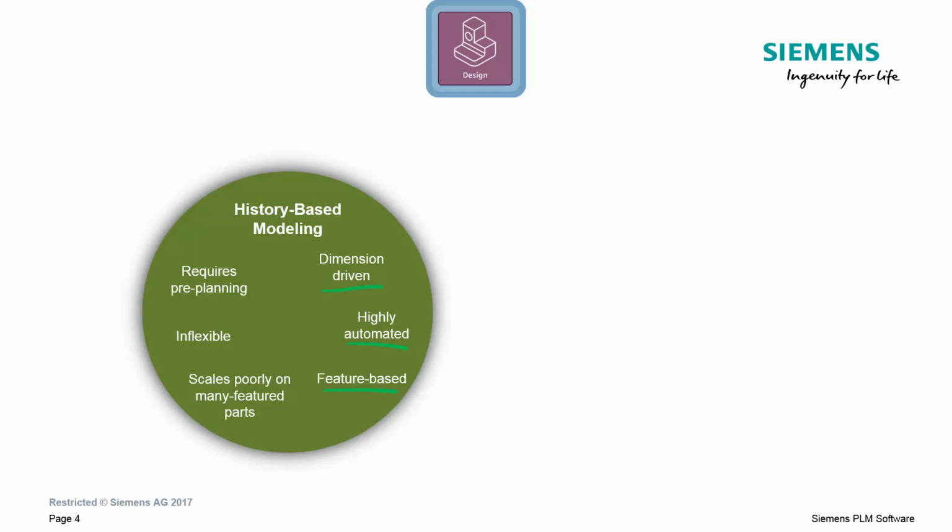For example, if a change needs to be made to a feature created early in the design, the edit must take place on the model at the state that it was in when that feature was created. Once the edit is made, all features created after that point have to be recomputed based on the new inputs, oftentimes breaking downstream features. This forces designers to carefully plan out how they build the model, otherwise the simplest edit could turn into a lot of time in remodeling.